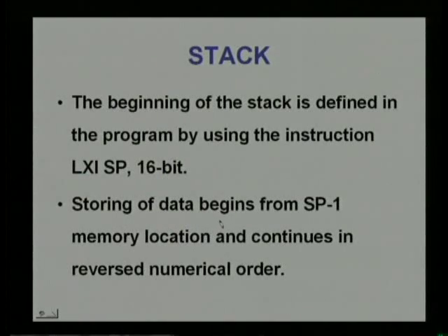Storing of data begins from stack pointer less 1 memory location and continues in reversed numerical order. In stack we store data by using stack related instructions, and data will be stored from bottom to top. Hence, while taking data out, the last entered data has to be taken out first. This is called last in first out method.